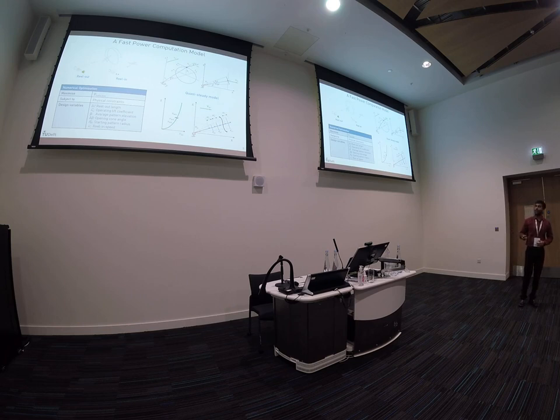The model is implemented as an optimization problem with an objective of maximizing the electrical cycle average for every wind speed, subject to multiple physical constraints, but basically finding the operational set points for each wind speed. That is the reel-out length, operating lift coefficient during the cycle, average pattern elevation, cone angle, starting pattern radius, and some ground station related parameters, that is the reel-in speed. Constraints are like your winch can only have a certain maximum speed, such constraints.